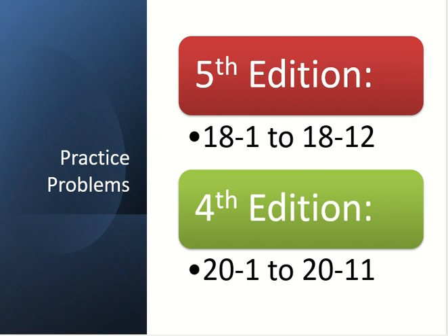Saturation flow rate means that if you come to the intersection, there is no signal for one hour. The signal is green for one hour; before you came, it was green, and for the next hour it will remain green. So that is saturation flow rate. This cannot be the actual capacity.